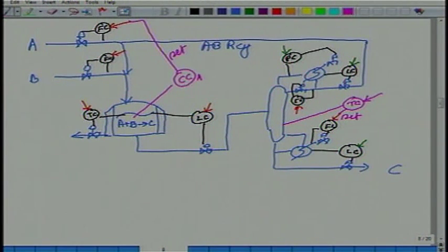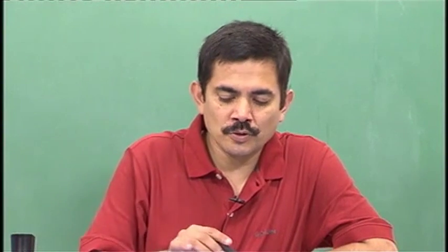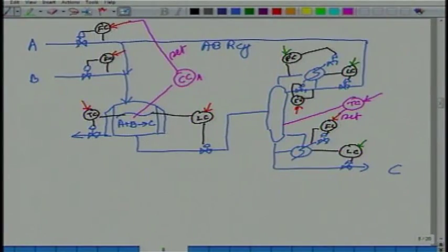Is the question clear? Do not struggle too much, this will work, okay, because if too much B is building up, A composition will go down, you will reduce the A, then A will match B, okay. If A is building up, A composition will go up, you will reduce the A, ultimately it will again match B, yeah.